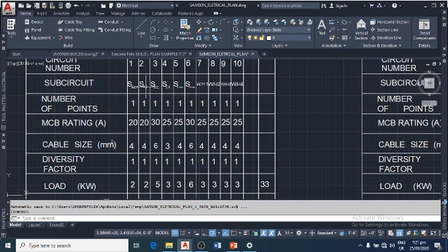The SP1 is the pump we're using. It's a 2,000 watt pump. The cooker unit, we have a 5,000 watt, that's 5 kilowatts. For this we have 3 and the rest. Then for our water heaters here we have 3 kilowatts each water heater. Then if you add up all the total load here, you have 33. Simple as that.